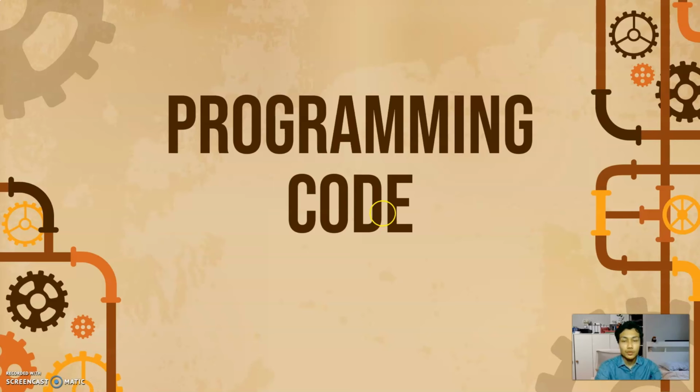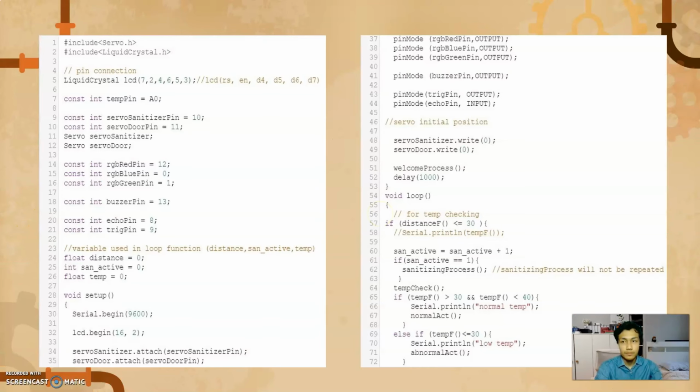So today I would like to present about the programming code. So the code that we use from the libraries are servo.h to control the servo and liquidcrystal.h to control the LCD module. From row 5th to row 21st, it shows the pin location between the Arduino Uno pin connected with the component. The variables that we use in our looping function are distance, send active, and temperature.